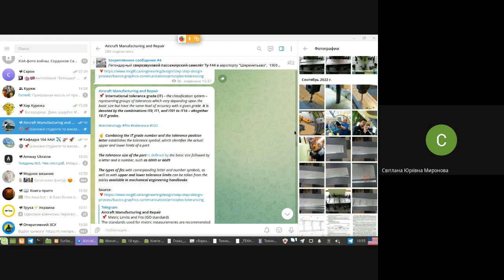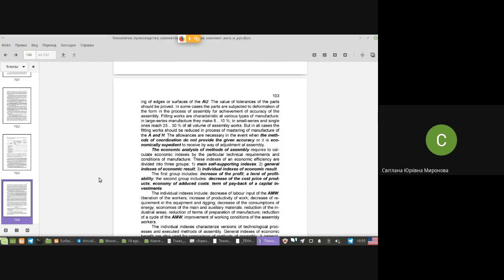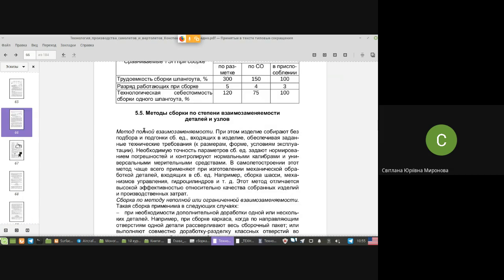So the technique of full interchangeability doesn't work in our case, just because we have a problem with part stiffness. And once again, it's a great technique in assembling because it's able to provide full interchangeability, and it's fast in assembling, and it does not demand any additional time and expenses for preparing of assembling, as we have no need of jigs, especially special jigs.